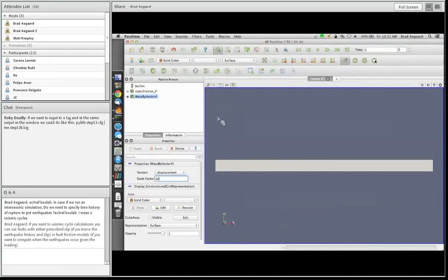So here I'm going to step through this. You'll see we exceed our friction threshold and start to deform. Notice that in this dynamic problem, rather than the deformation immediately reaching the edges of our domain, the deformation is being transferred by the seismic waves, and so the ends of the bar don't move until the shear wave can propagate down the bar.